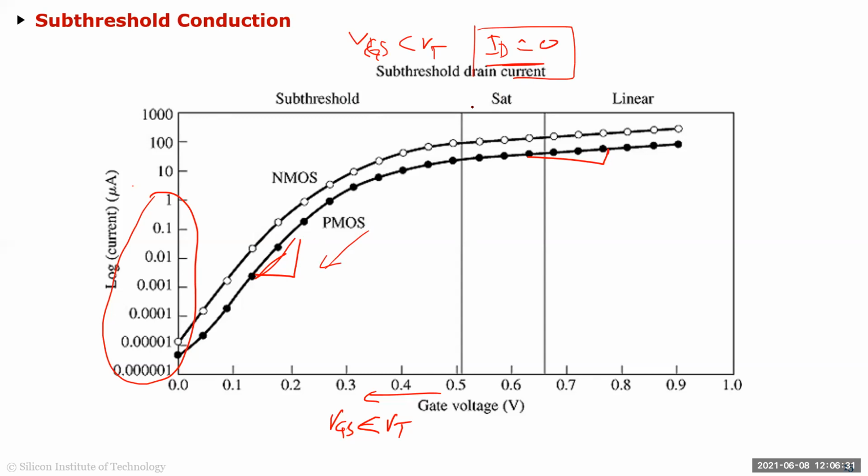And the models now, see when I started designing, back in the late 90s, nobody ever used subthreshold region to fabricate a chip because the models were so bad. When the chip came back, it would be completely off. Your chip essentially would be dead because the models were very bad. But now the models are very accurate. So you can actually drive it into subthreshold, and whatever your simulation is showing you, when you get your chip back, it'll be like 99.9% accurate.